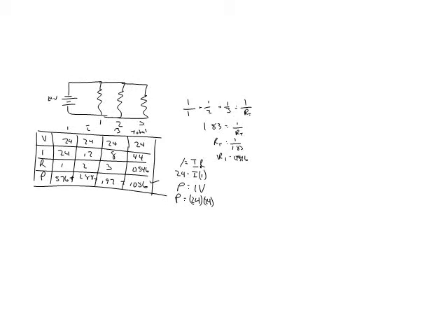So Kirchhoff's laws are used to find the current flow in the circuit, or they use the current flow to figure out stuff in the circuit, like missing resistances, voltages and currents. One of the things that you need to remember is that the flow of electrons is actually opposite to the direction of the current. Just have it in the back of your mind. I don't think it's going to hinder you too much if you forget.